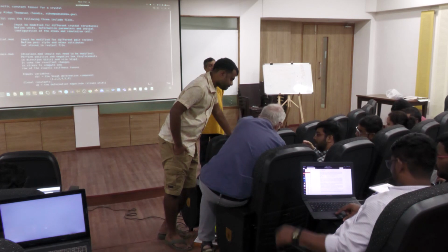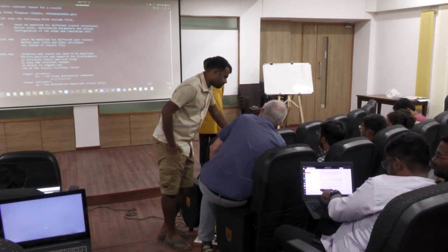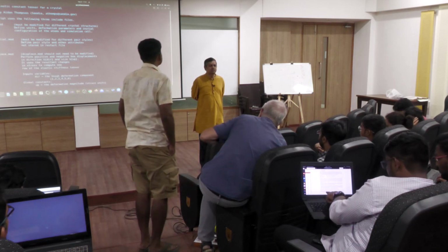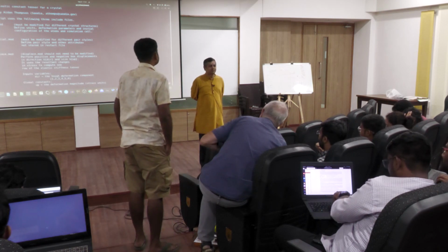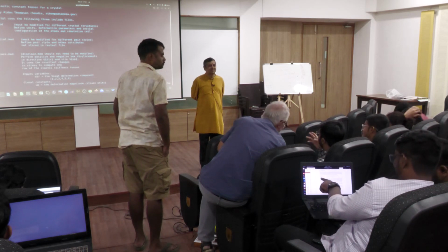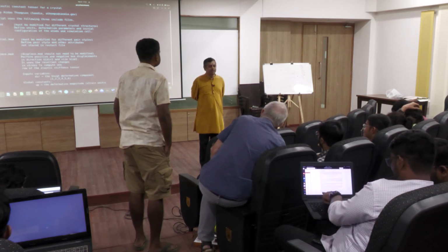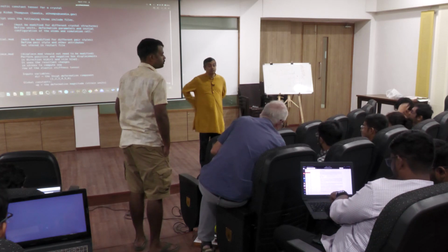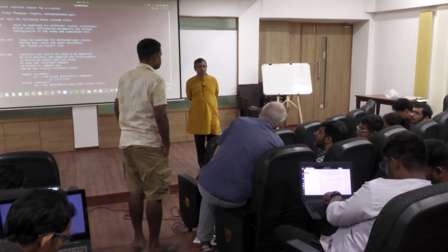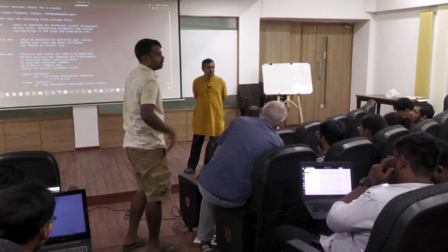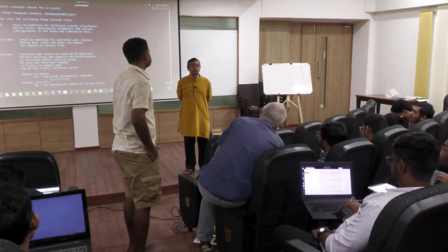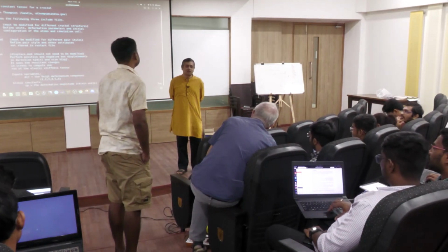It's always this ADIOS package which is missing. I couldn't fix it either. The only solution was to remove everything and redo it, now using make yes all, and that worked for me after 3-4 times. I also made this mistake, CMake and then make, and that also doesn't work.